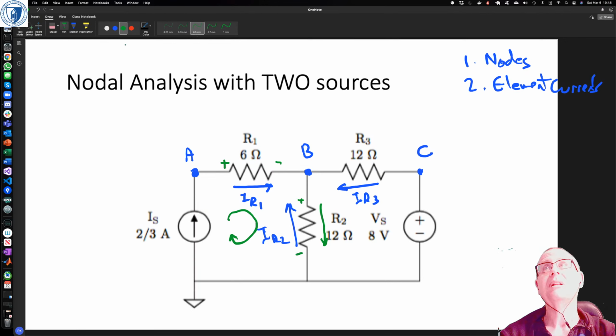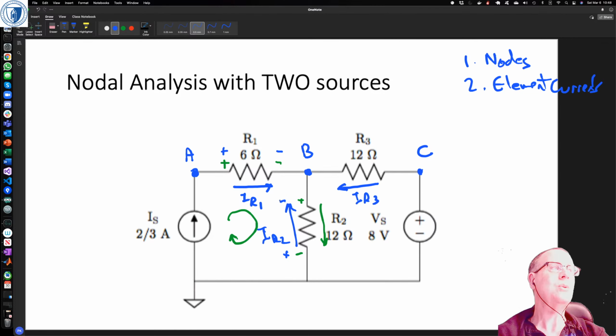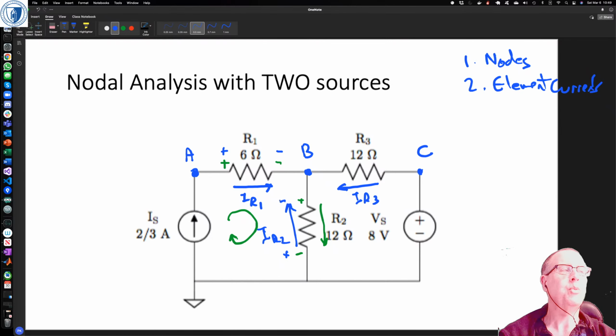The trouble is now I'm choosing them different polarities. So it should still work. It's just that you wouldn't want to do KVL analysis this way, because you'd have to be very careful that you've got the signs all right. That's why we choose mesh currents for mesh analysis and make sure that everything's flowing.